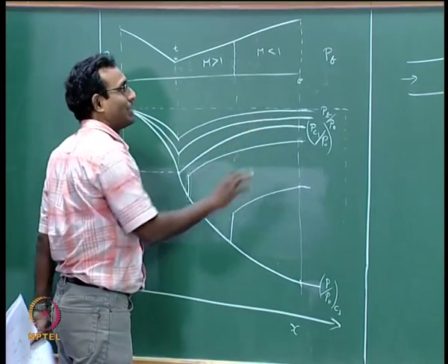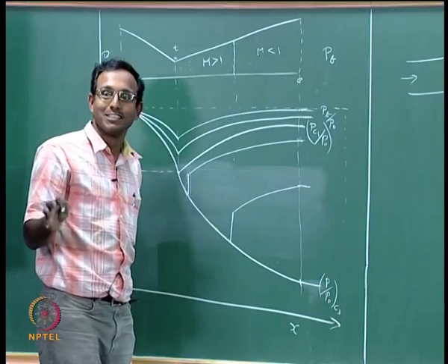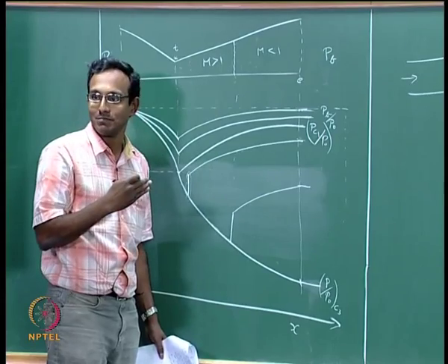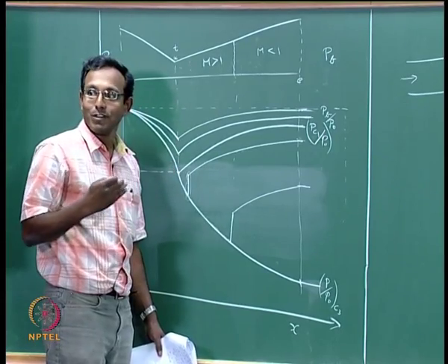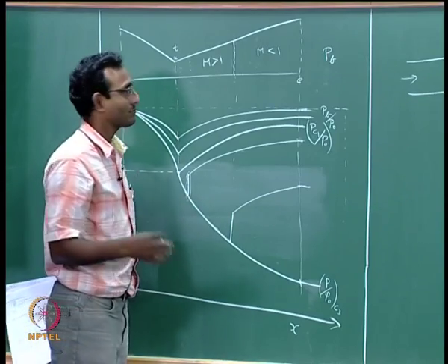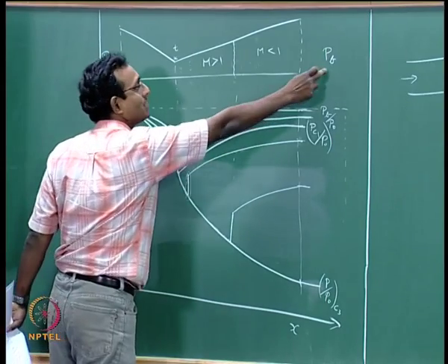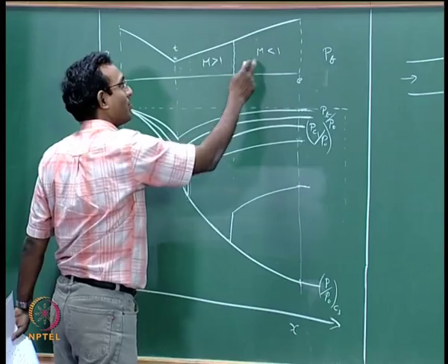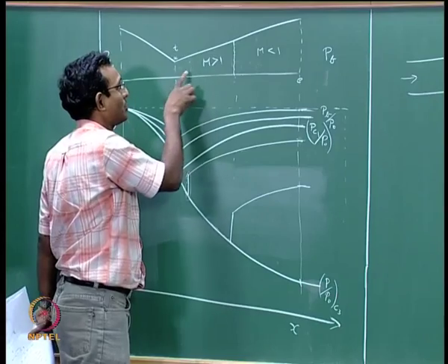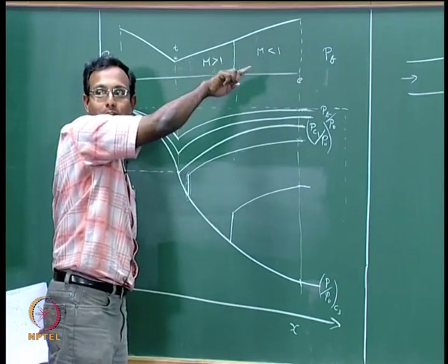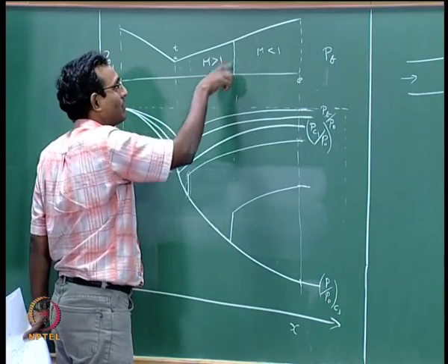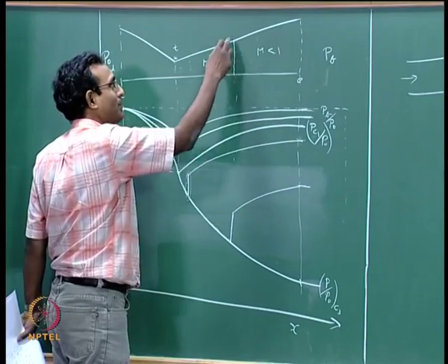Okay. Now we will assume all that unsteady stuff is not present in the current world, because we are thinking of quasi-steady problems. We are making changes but we wait for infinite time after that. We will not worry about what is really happening during the unsteady motion. So I decreased the pressure downstream, so there is an expansion wave coming in and weakening the shock which was originally here, and because of that the shock is pushed by the flow more downstream. But as it goes more downstream the Mach number changes, and because of that the shock finds a nice place to sit.